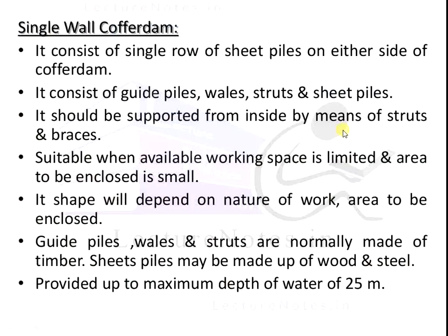Okay. Next type is the single wall cofferdam. It consists of a single row of sheet piles on either side of the cofferdam. It consists of guide piles, wales, studs, and sheet piles. It should be supported from inside by means of straight studs and braces.